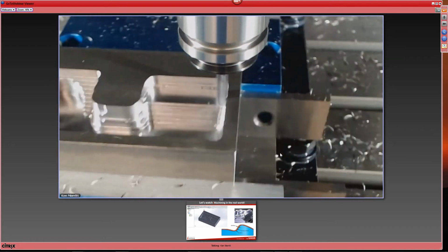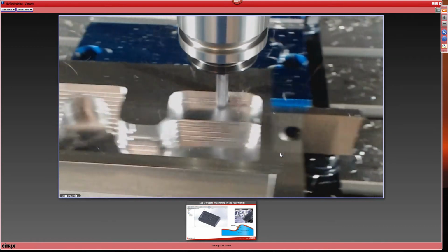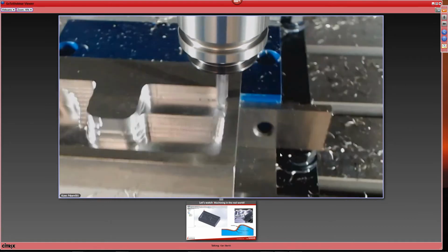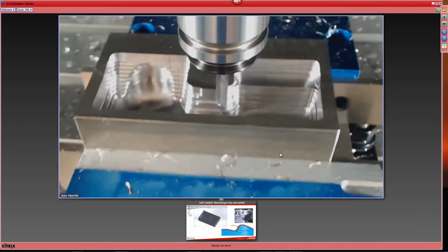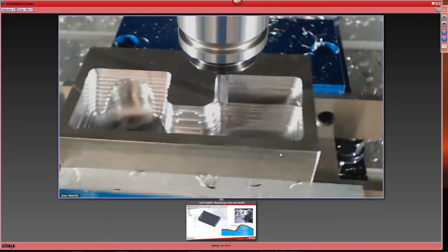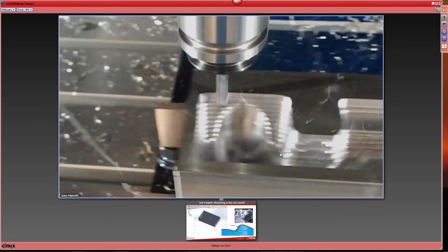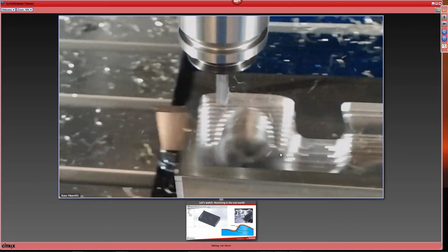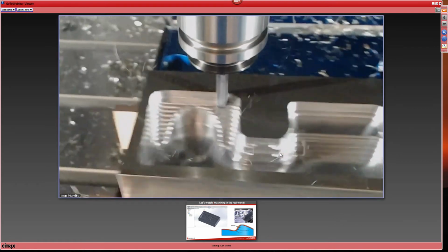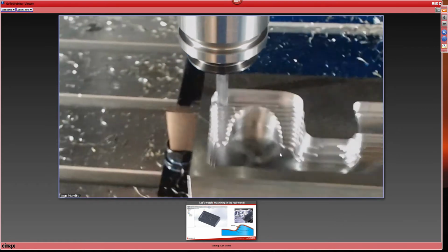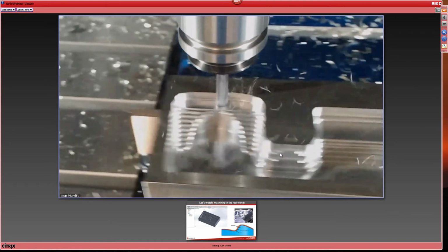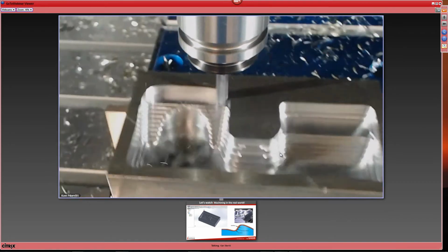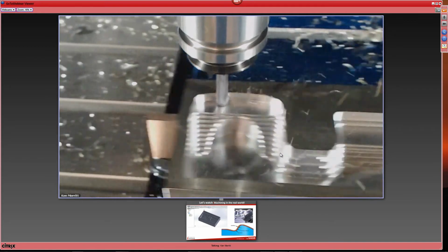Most people over the years have resolved that issue by running a semi-finished toolpath with a much coarser step over, but that reduces the remaining stock to a fairly consistent level over all these surfaces. That alleviates the problem of the uneven loading and unloading of the tool. One of the cool things about iMachining is it does that all within the roughing operation.